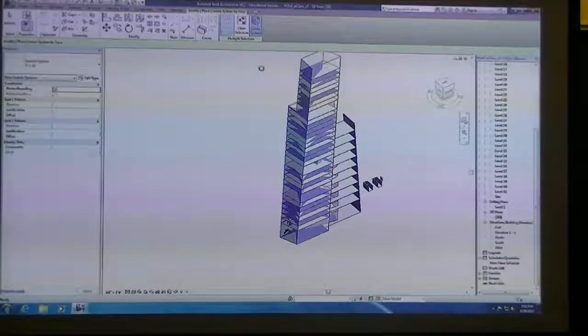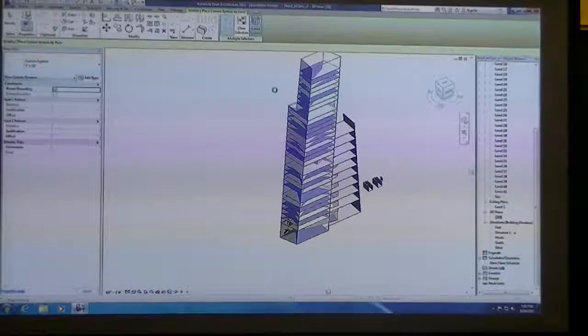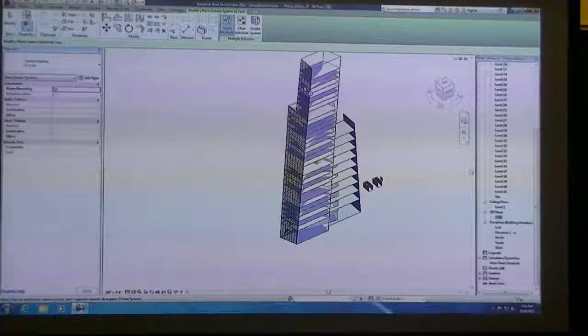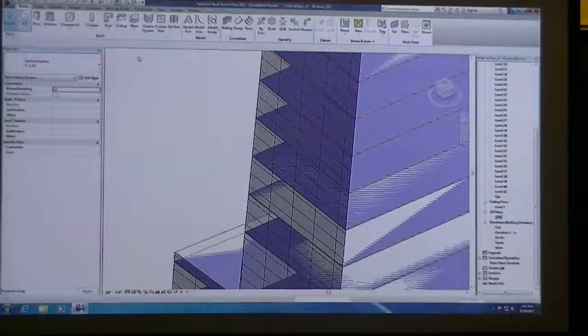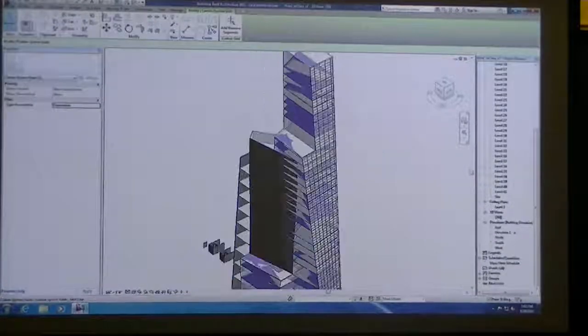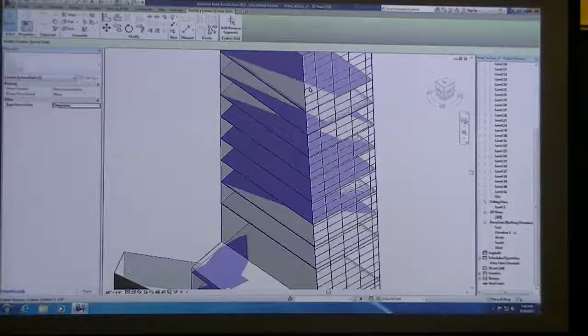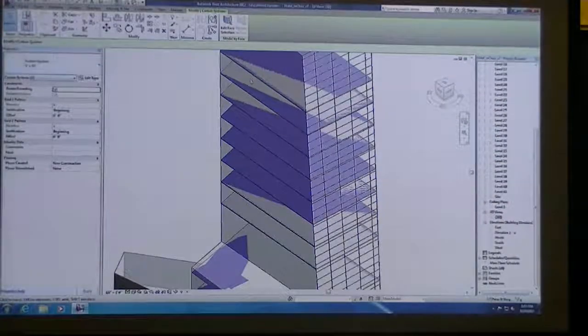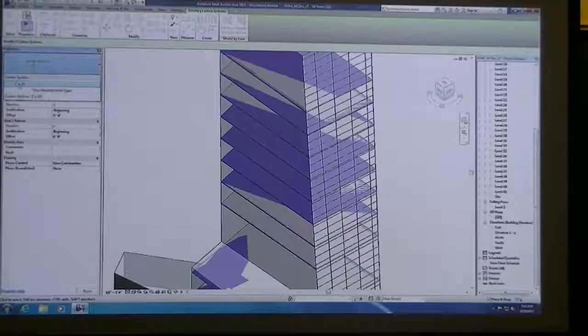It might take a moment here. This will create a bunch of grid lines associated with your form. And if you tab over this system so that you select the whole entire thing, you can see that you have a couple settings here that talk about the number of grid patterns and justification, and kind of similar to the curtain panel assemblies. It's just you don't have the ability to select curtain panel pattern-based elements.